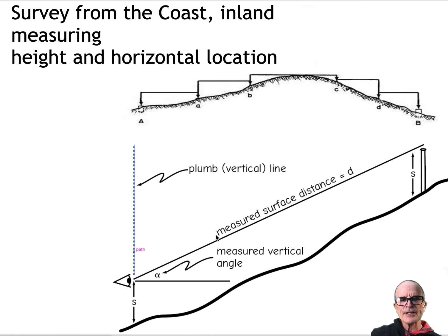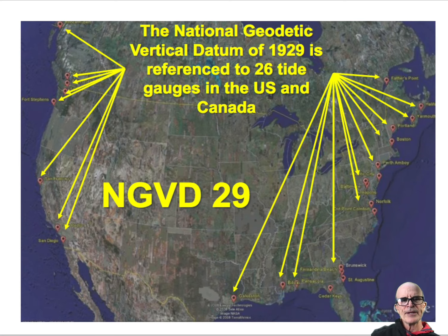We don't have to do these leveling surveys across space, because at each turn of the leveling survey we accumulate error. We make small measurement discrepancies, and by the time we get to the middle of the country, that error has compounded so that our measurements aren't as good as they could be. The reason we've come to this system and we don't use a sea level based system is that the old one, the one prior to the 1980s, was the National Geodetic Vertical Datum of 1929, and it started at a bunch of benchmarks at well-measured tidal gauges, and then they surveyed inland with these leveling surveys.